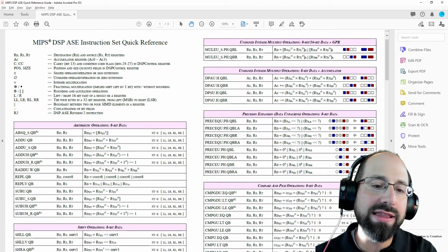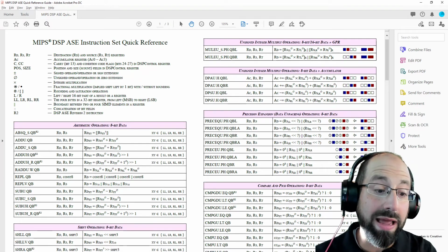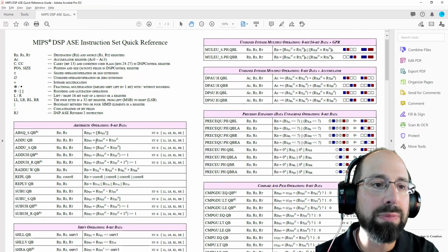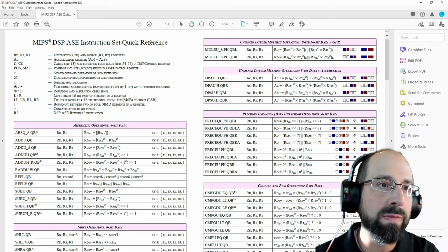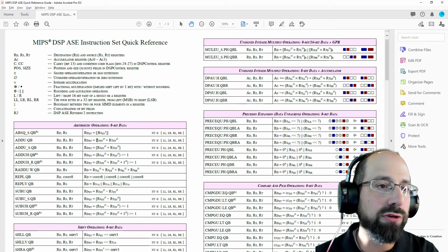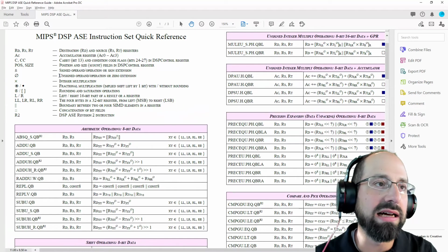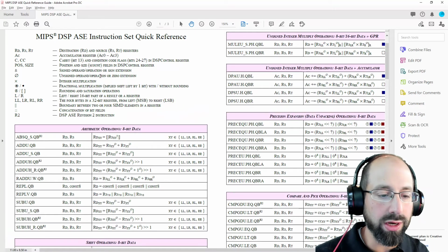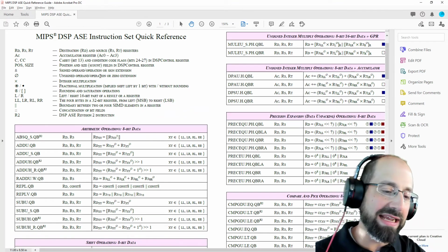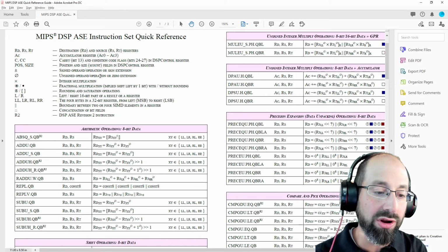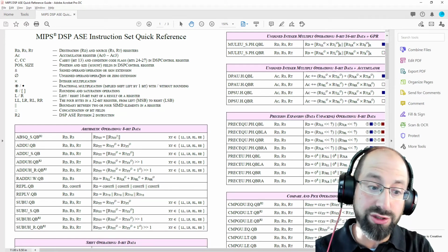And the answer is there in the data sheet, but it's pretty obfuscated in terms of what the spec is for these instructions. There are a couple of different things provided as an answer to that question of how we deal with overflow. The first, for just the regular addu, is that little symbol here that's specifying that these are unsigned operations. So we don't have to worry about the project part A calculation of overflow with regards to adding two negatives and getting a positive result back out. We treat these as 8-bit unsigned quantities to start with. So that flavor of overflow is not an issue for us.